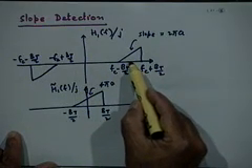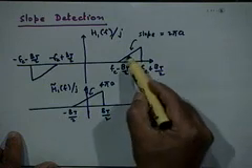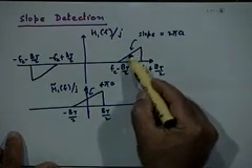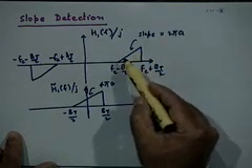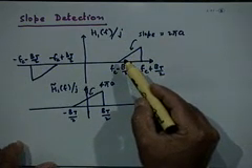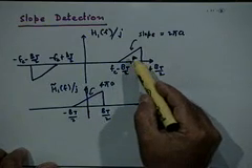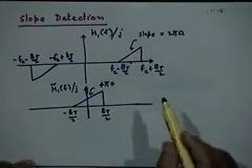As the input frequency varied around FC, the response of the circuit would vary linearly in this fashion. That is the slope detector.